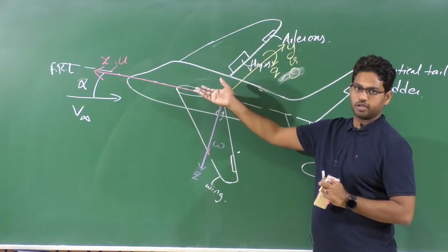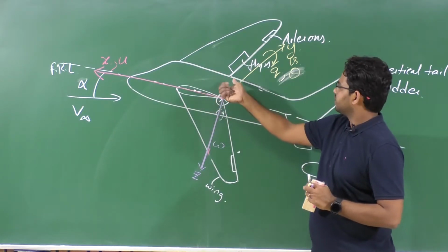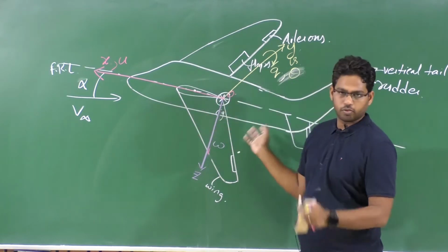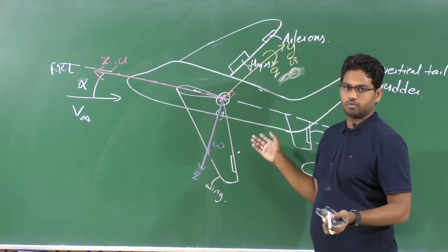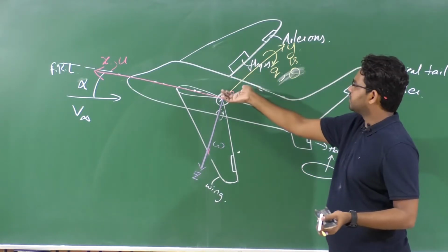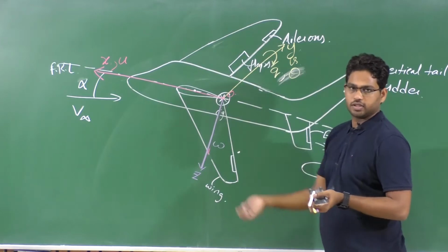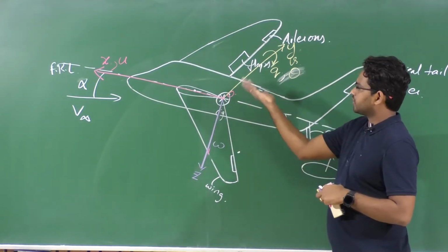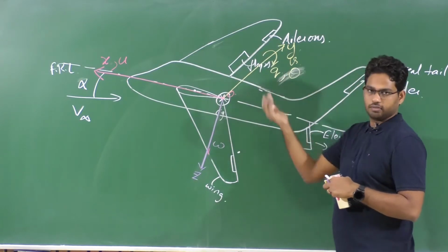And if the aircraft rotates its nose down due to that moment, we call it pitch down moment, right? And it is considered negative. And q is considered positive when it is pitching up, when the rate is changing in the nose up direction, and theta is also considered positive when the aircraft nose is up, right?